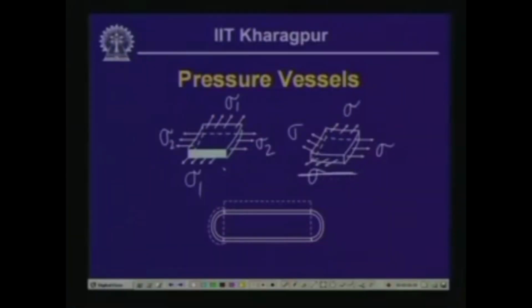In case of cylindrical pressure vessel, this longitudinal stress does not really contribute much to the equilibrium of the curved surface, whereas in case of spherical vessels, the stresses from both directions come in resisting the pressure exerted by the content, and that is the reason the stress in the cylindrical one is more than the spherical one. In case of spherical vessel we have uniform tensile stress over the entire surface, which we normally call the membrane stresses.